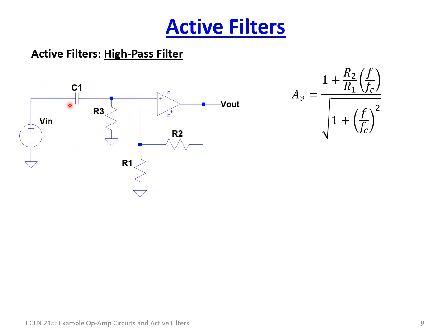Again, the advantage of this is no matter what the load is, we are now isolated. Of course, you can even put another amplifier stage on the front end. You can put a buffer amplifier, so it truly isolates the filter section from any input-output effects. And of course, it has the exact same cut-on frequency in this case of 1 over 2 pi R3 times C1.